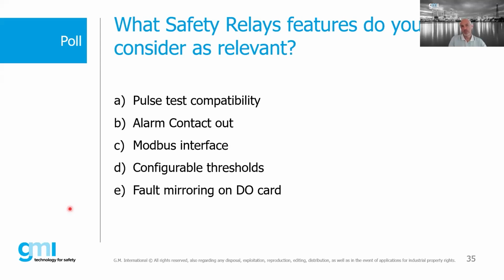But we see that in projects people are asking more and more for this topology of relay, because when you use external relays, you drive the coil, you close or you open the external relay, but you never know if your load is activated as you wish. So the line monitor gives you these extra features, and you can detect what is really dangerous undetected and turn it into a dangerous detected failure that enhances your SIL level.